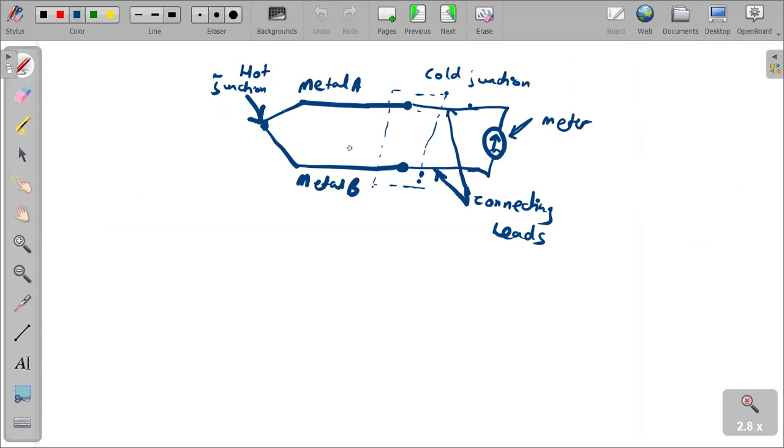So I need us to know that, as I have said, it is a sensitive temperature device. It's a temperature sensitive device. So it is made up of two metal alloys. So you see metal A and metal B, for example, mostly one is nickel chrome, and the other one can be nickel aluminum. So metal A and metal B that you are seeing there. Then the conductors are typically built into a cable that has a heat resistance sheath.